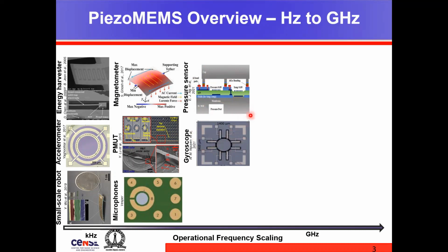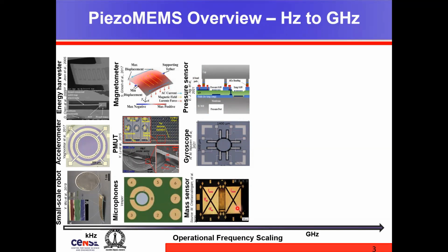Support transducer topology has been used to excite high-Q bulk modes, and they are deployed as rotation rate sensors, also known as gyroscopes. Mass sensors, whose readout mainly depends on amplitude ratio and frequency variation, have been widely adopted in PiezoMEMS for environmental sensing applications. PiezoMEMS are commonly used for PM2.5 pollutant sensing. Resonators with metasurfaces on top of the electrodes, as you can see over here, we have a nanoplasmonic metasurface, are used to attain wavelength selective infrared sensors.